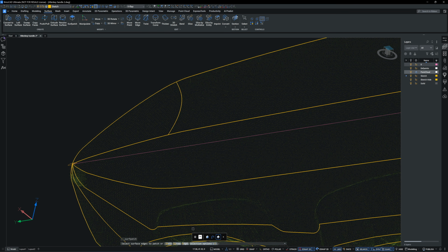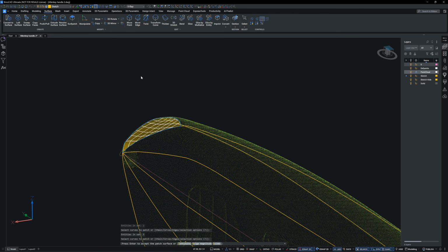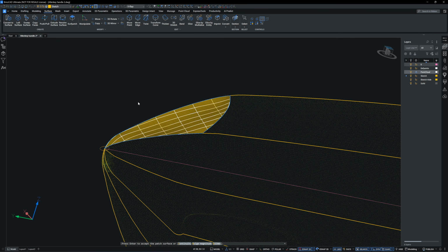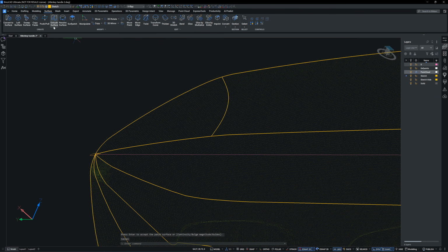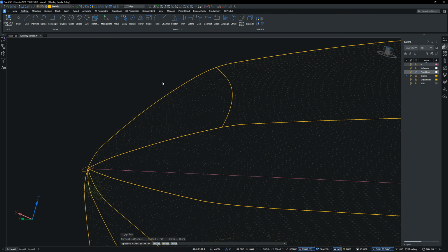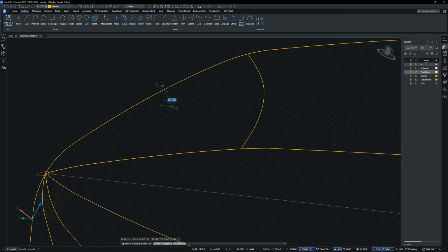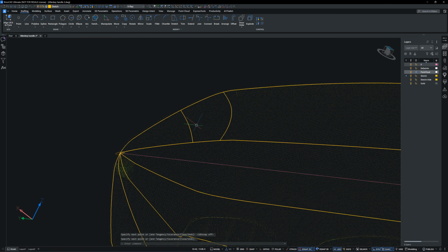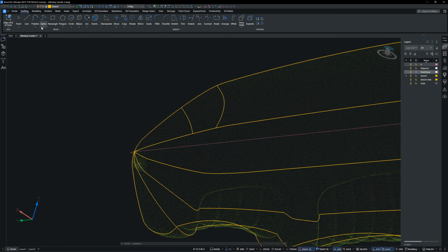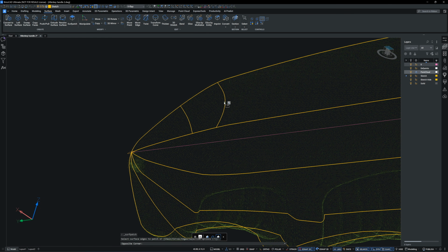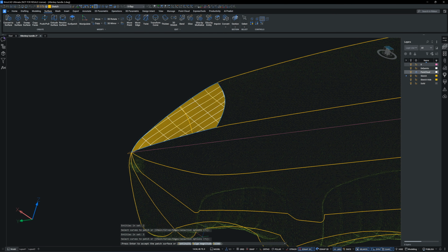You need to activate the 3D snapping tool by pressing the F4 key to snap the spline onto the point cloud, and then deactivate it when snapping onto the 2D curves. This approach ensures the spline lies exactly on the handlebar surface. If you trace the 2D sketches accurately, the surface will blend smoothly.